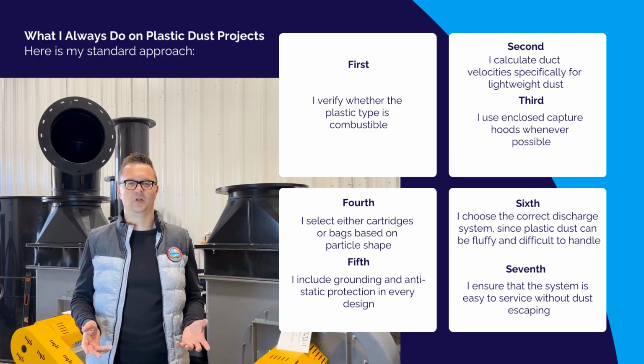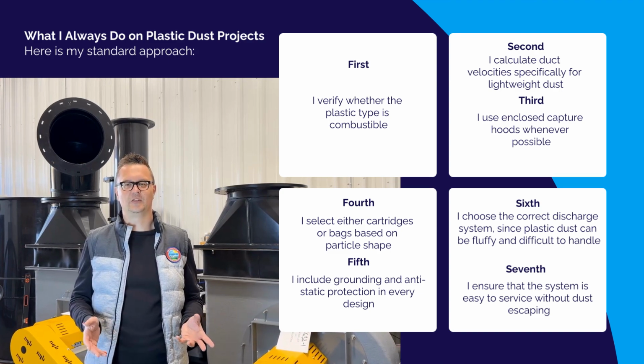Fifth, I include grounding and anti-static protection in every design. Sixth, I choose the correct discharge system, since plastic dust can be fluffy and difficult to handle. Seventh, I ensure that the system is easy to service without dust escaping. These steps create a stable and efficient system.